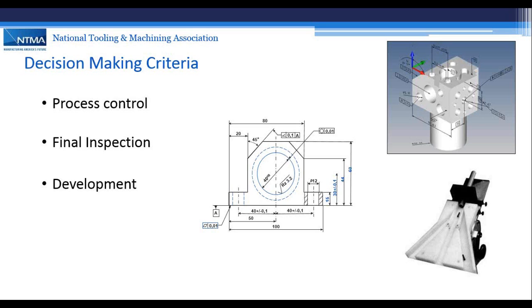Measuring systems have to be chosen for looking at prototypes. And here it's a matter of managing the uncertainty of a measurement system compared to the tolerances you're trying to generate and control. So a gauge decision, flexible or dedicated, is based on those foundations of a sensor and where you plan to use it. Right.